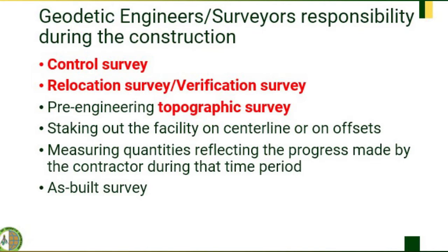So if we don't have control points, then we just arbitrarily select points, but that would be not economical because tendency will be having some encroachments because we did not establish the boundaries well and so on. Yeah. So that's why it's very important to conduct a survey or pre-engineering surveys before the construction proper.